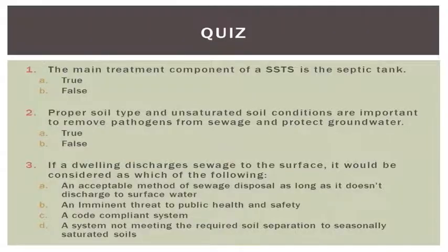So we'll complete session 4 with our quiz. Question number 1 in our quiz is, the main treatment component of an ISTS is the septic tank. Is that true or is that false? Question 2, proper soil type and unsaturated soil conditions are important to remove pathogens from sewage and protect the groundwater. Is that a true statement or a false statement?